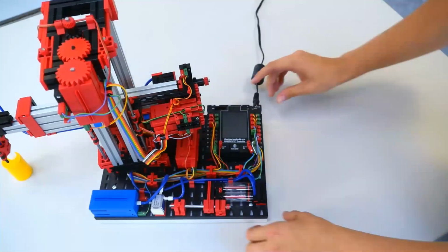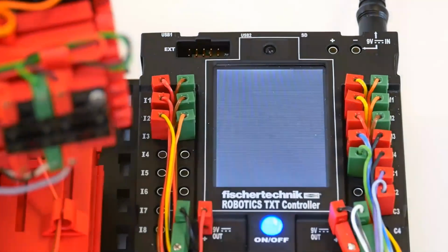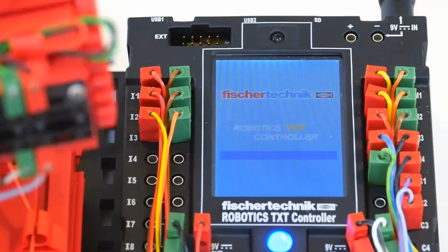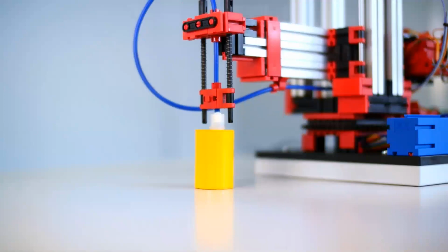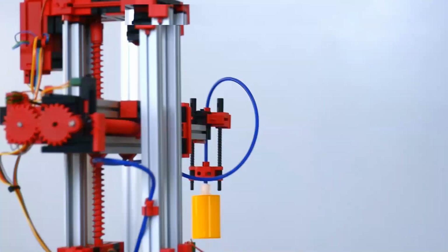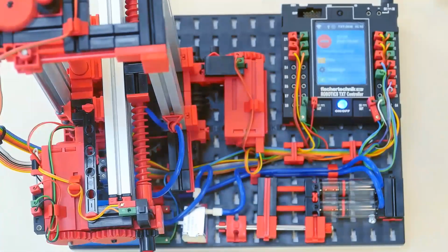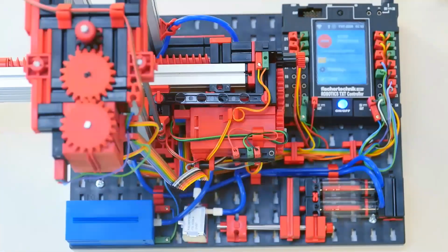The model's dimensions are approximately 9 by 19 by 15 inches, and it has a weight of about 7 pounds. Now, the 24-volt versions of this model, as well as the other 24-volt versions we're going to be looking at, each have a relay board for motor polarity reversal and both a multi-pin connector with 26 pins with a grid of 2.54 millimeters, as well as additional PCB terminals with push-in connections for all inputs and outputs.